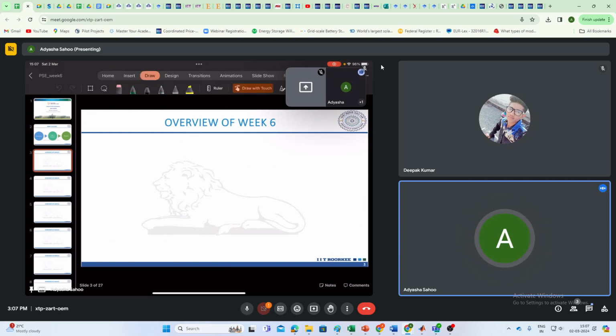So, for this week, we will be discussing the concepts for sag and tension. So what is this sag? Let's say you have this conductor which is supported between two towers. Due to the weight of this conductor inherently, instead of being stretched tightly between this support, it will have some sag, which is represented by the distance d here.